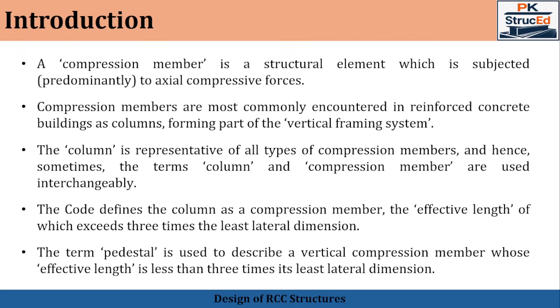Now, a compression member is a structural element that is subjected predominantly to axial compressive forces. In reinforced concrete buildings, compression members are most commonly encountered as columns or pedestals. So columns form the vertical framing system of a structure, which are responsible for transferring the loads from the slabs, beams as well as the upper floors safely down to the foundation.